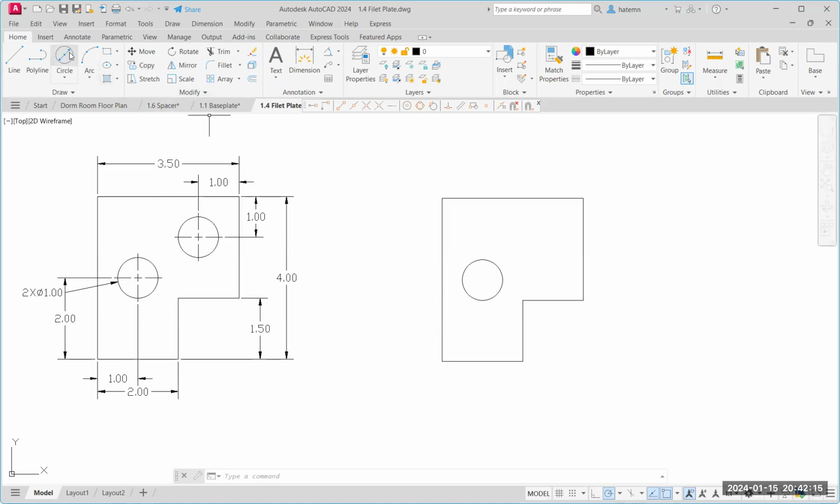Again, we're going to start off by choosing our command. We're going to draw this circle, which is in a diameter. And notice instead of this bottom left-hand corner, the measurements for the center point are actually on the right, upper right corner. So instead of placing my circle here and moving it, I'm going to do something called snap from, and I have a toolbar here to use. So you probably don't already have this toolbar. So let's first find out where it's at.